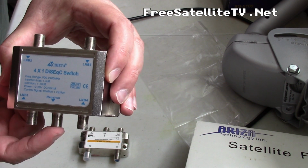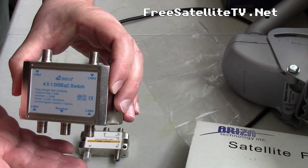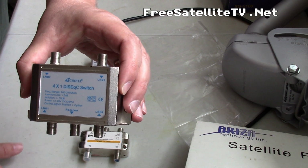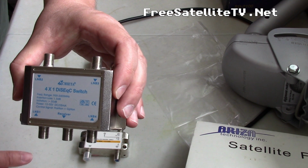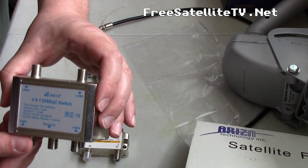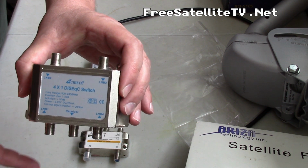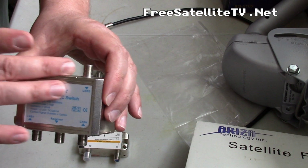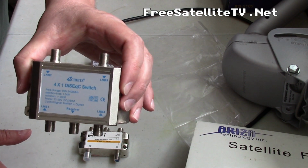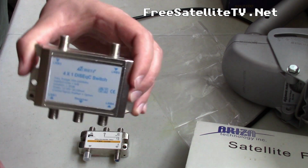This is where your receiver goes, and you can have multiple LNBs or multiple dishes. Now in my setup, I have a couple dishes in my backyard. So I'll have one LNB going to different dishes. My LNB1's always my C-band, because C-band's most of what I watch all the time. And then anything else is pretty much Ku band, because I have two extra Ku band satellite dishes. So I'm really using like 3 of these, but then there's a 4th one I'm not using.